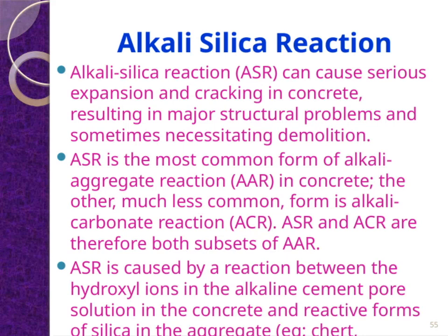Let's talk about alkali-silica reaction, or ASR, which can cause serious problems in concrete structures. When ASR occurs, it leads to expansion and cracking, and in some cases, it can be so severe that the structure needs to be demolished. It's important to understand that ASR is actually the most common form of alkali aggregate reaction, or AAR, in concrete. There's also a less common form called alkali carbonate reaction, or ACR, but overall, both ASR and ACR are subsets of AAR.